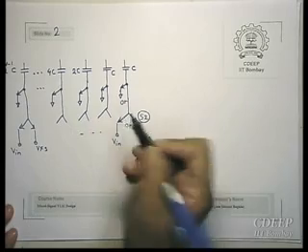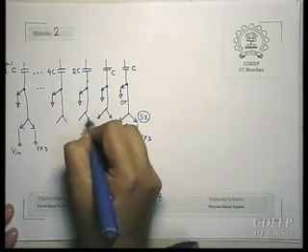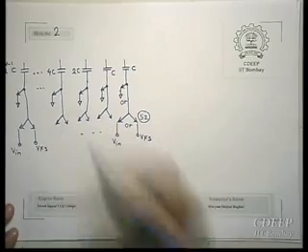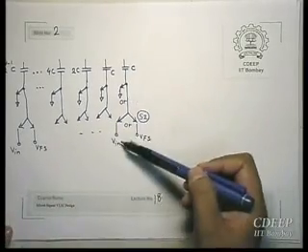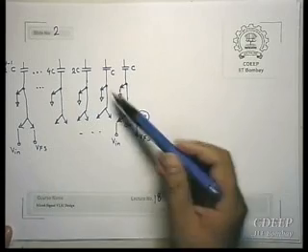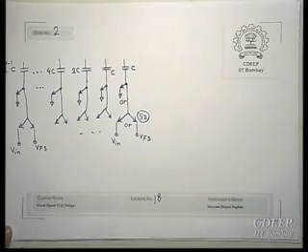these transitions happen at the same time, in the sense that if you connect the bottom plate of C to V in, all will get connected, or all will be connected to V full scale, or any one of them will be connected to ground.